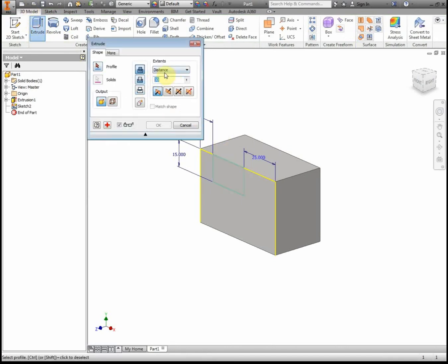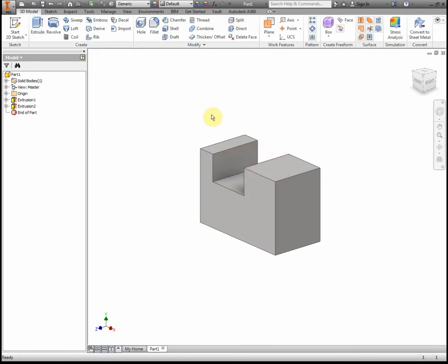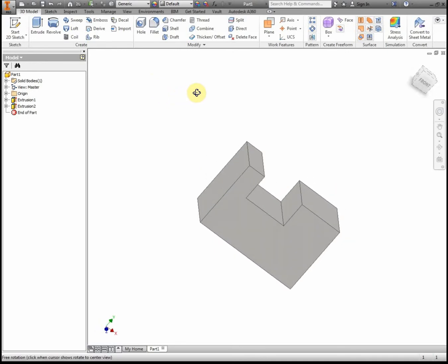3D model, I'm going to extrude. I want to extrude this not just 30, but all the way through. And I want it to be a cut, so I choose this piece here. And I have to now click on the element I want to cut out. It's showing me a preview, and now I hit OK or enter to make sure this is what I want. By pushing down on shift and pushing down on the scroll wheel like it's a button, I'm able to orbit around to make sure it cut all the way through.